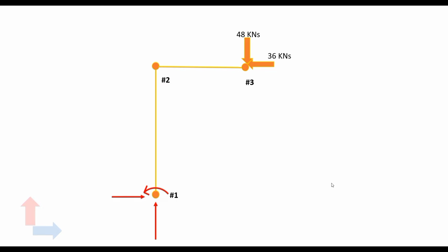Now remember that with the given configuration of the x and y axis, the positive direction of the z axis would be pointing out of the screen towards you. And thus, if you consider the right hand thumb rule, any anti-clockwise movement or rotation would be considered positive, and thus the moment reaction is shown in its positive sense in the anti-clockwise direction.